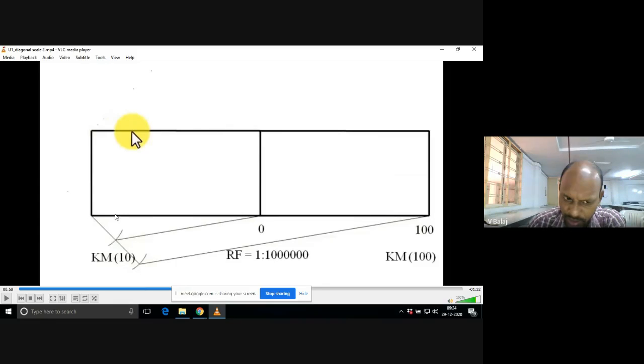20 centimeter you got, right? The length of the first line, the baseline, is 20 centimeter. Height you can take 4 to 5 centimeter, right? And after dividing, numbering it as 0 starting from here, leaving the first part, you can mark 0, 100 kilometer. Left hand side there is one more 100 kilometer, total 200 kilometers. Okay, so this 20 centimeter is representing 200 kilometers outside.